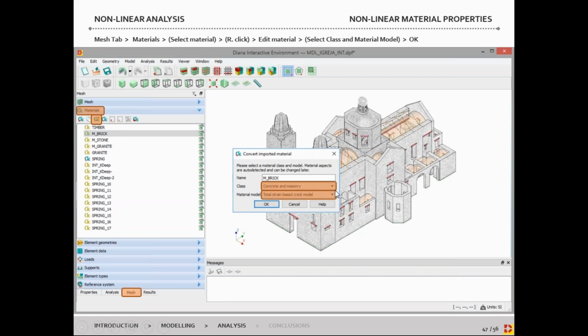Here you can define different material models depending on the type of analysis you're going to run or the considerations that you have for your materials. Also, it is advisable that if we have shell elements, or elements that by default have 1 integration point along the thickness, we come here and, for the nonlinear analysis, increase the number of integration points. If you work with the previous version it was this command, and with the new versions it is this command.